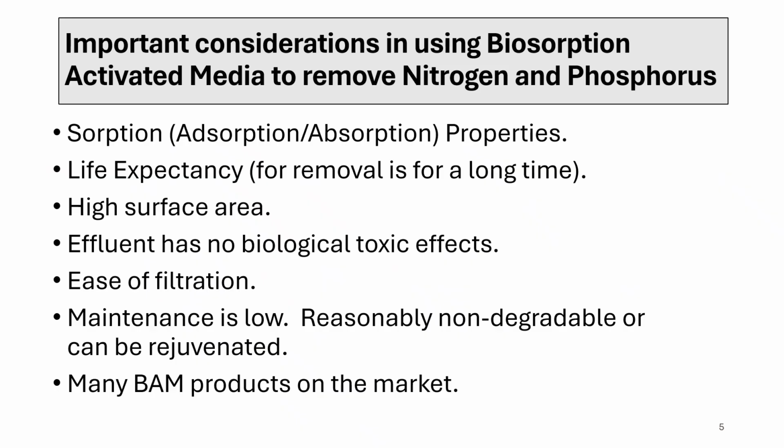When selecting a biosorption activated media for removing nitrogen and phosphorus, there are several important factors to keep in mind. First and foremost, you want to understand the sorption properties of the material, meaning how well it adsorbs or absorbs these nutrients from the water. This directly determines how effective the media will be in your application.